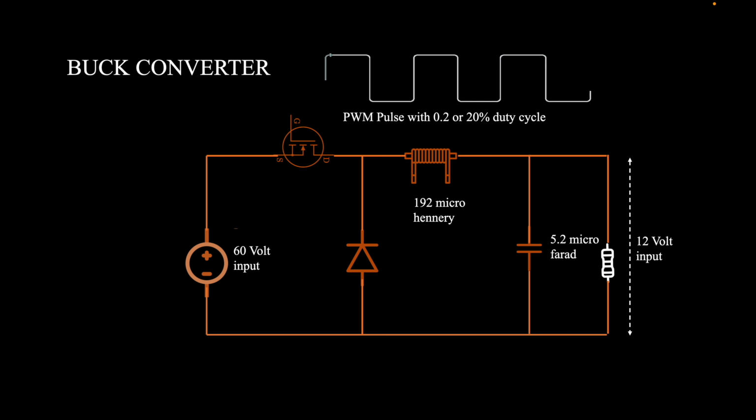It should be the same when you are at switch off. There will be no negative current flowing through the circuit because the diode will be blocking the negative current. In the initial stage, when you switch on, whichever current flow is there, the same current flow should be maintained in the inductor or in the entire circuit because of the diode opposing the reversal of the current.